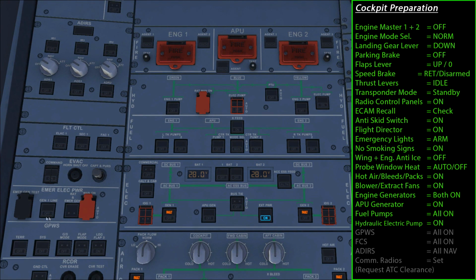After that, we want to check the ground proximity warning system, and we just want to make sure that all of these systems are on. So again, when they're switched off, they'll light up and show as being switched off, so we just want to make sure that all of those are on. The only thing that needs to be switched off at the moment is this landing flap 3 setting here, which is a bit of a special setting, so just make sure that all of these lights here are extinguished.